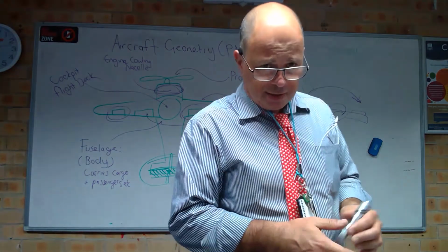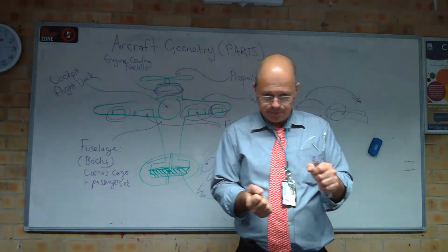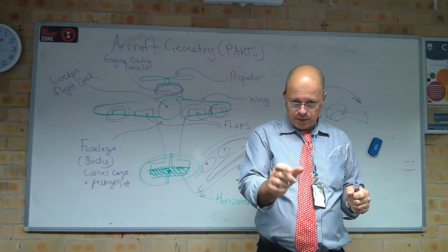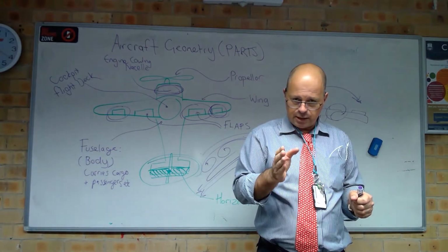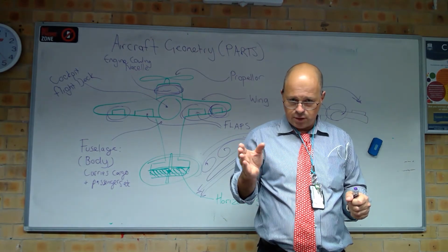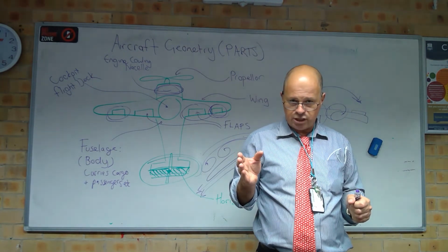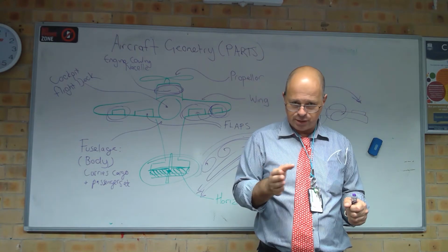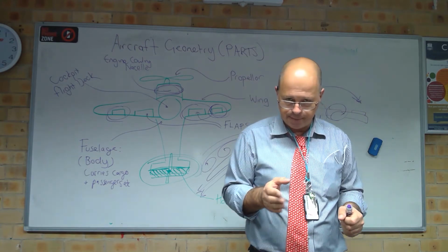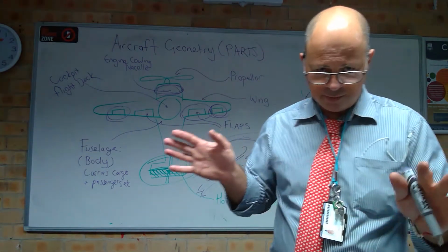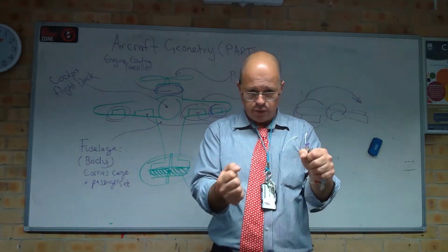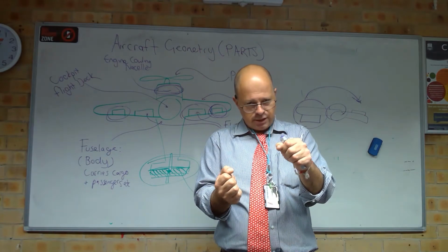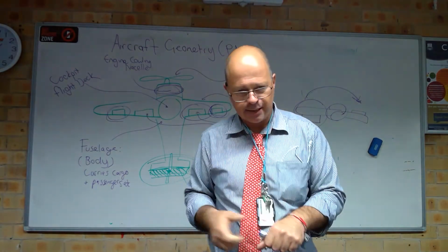And if you're doing a pilot's license and you do a right-hand turn, there's a little ball in a tube that you try and keep in the center. And so if the ball starts to go off to the right, they say you step on the ball. So you use your rudder pedals to keep the turn balanced, okay? Probably too much information, but at any rate, if you're turning to the right, you'd normally apply a little bit of right rudder pedal just to make the turn nice and balanced.